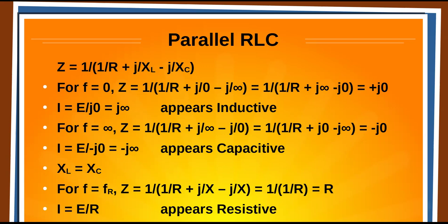The bottom line is you get just the opposite behavior. It appears inductive at low frequencies. It appears capacitive at high frequencies. And of course, it's equal to circuit resistance at resonance.